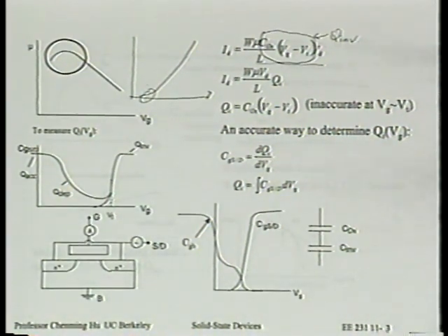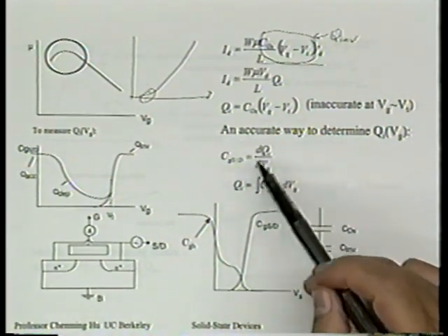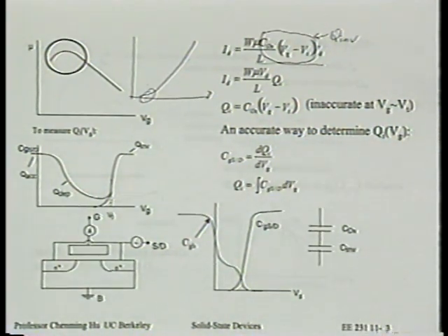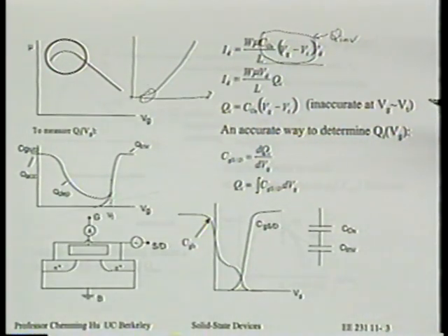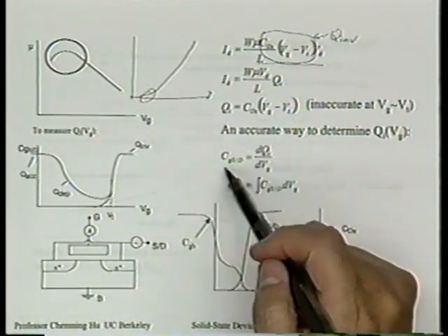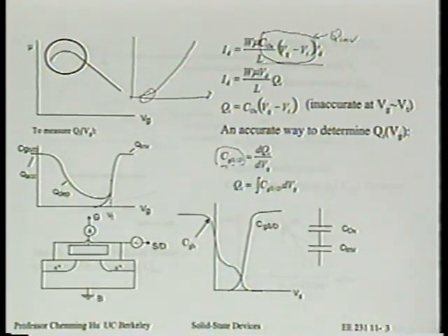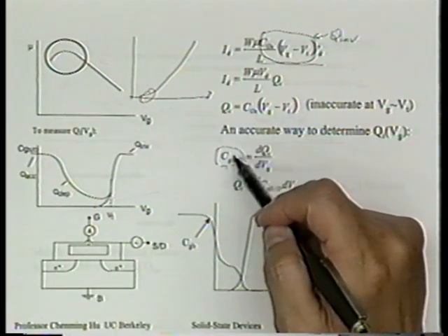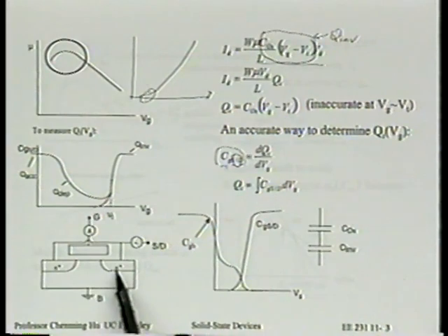And this goes back to the first few weeks of this course. We talked about capacitance. Capacitance is equal to dQ/dVG. We can limit ourselves to only look at the inversion charge if we measure only one component of capacitance called CGS/D, where S/D, meaning source and drain, are shorted together, as shown here.